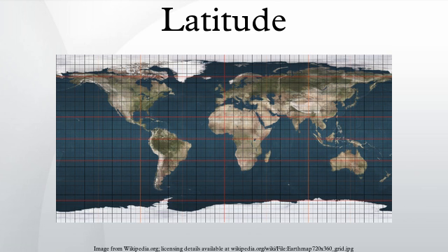In English texts, the latitude angle, defined below, is usually denoted by the Greek lowercase letter phi. It is measured in degrees, minutes and seconds or decimal degrees, north or south of the equator. Measurement of latitude requires an understanding of the gravitational field of the Earth, either for setting up theodolites or for determination of GPS satellite orbits. The study of the figure of the Earth together with its gravitational field is the science of geodesy. These topics are not discussed in this article.